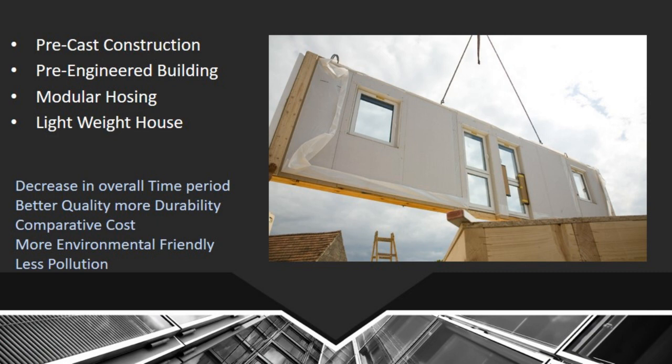So I can say, because 90% of the construction is being done with the help of concrete in RCC structure in India. In that scenario, the curing period which is advised is around 28 days. For that particular period, if you are running a parallel activity, then it is fine. Else your structure is being placed without any activity. So that could be the thing.